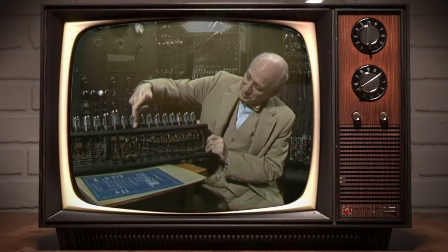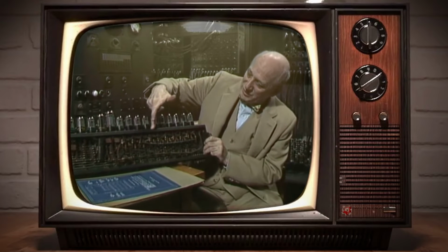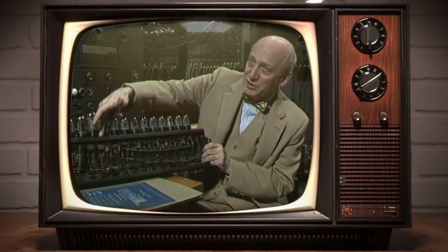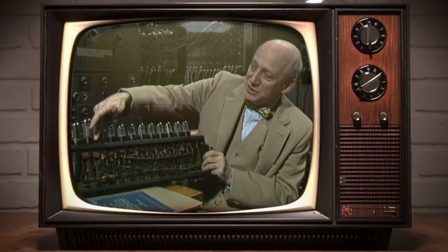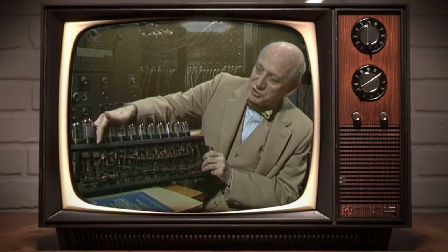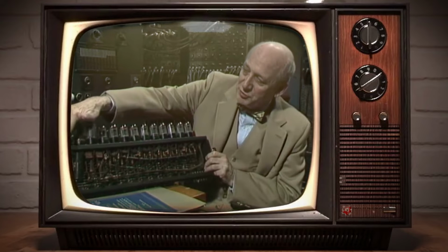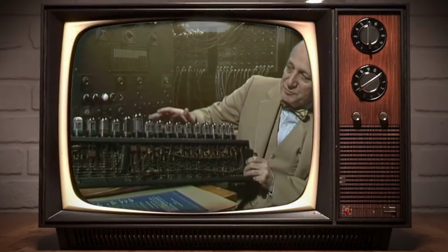We designed this circuit first before anything else. We tried 6 different circuits out and finally modified one of them and picked this one as the best one we could find. It had far more ability to count accurately and withstand changes in voltage and part values than any other circuit we could find. We nevertheless found it was critical of the shape of pulses that were fed into it, and so we designed a special circuit called the pulse shaper, which was found in these next 3 tubes here.